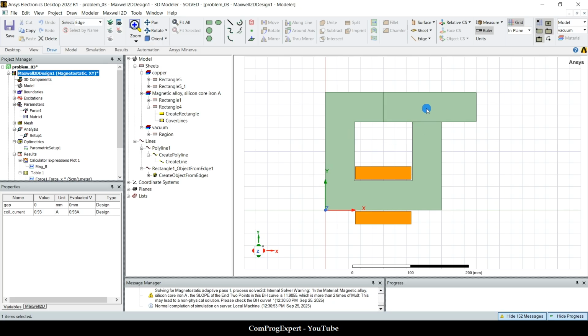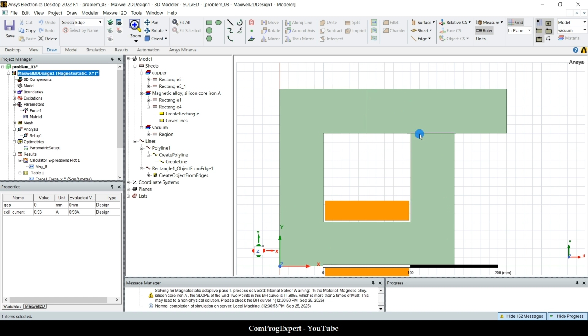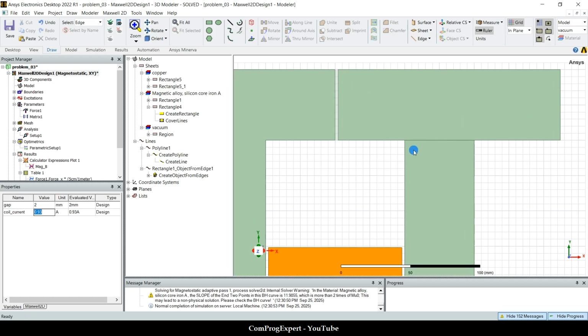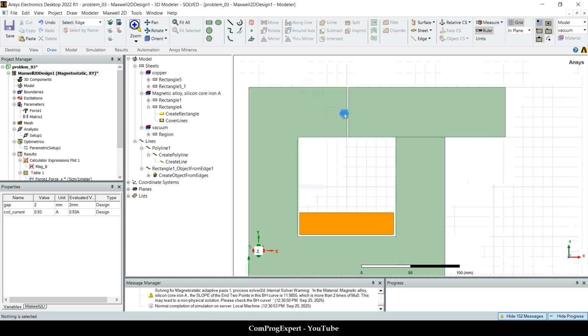So you can use this powerful software to calculate the force. Also, you can calculate the force manually, compare your numbers. We have these two air gaps. This air gap is closed, yes, even when we change this number, for example, 2 millimeter. This air gap is always closed. We have one element of the force here and one here on this moving part.